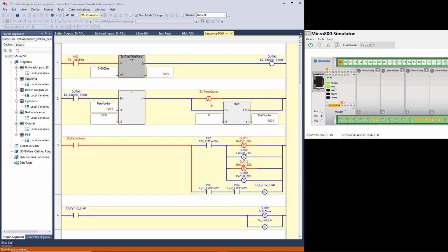do anything further, technically this part has gone through photo I1 and now it's going to pass through photo I2, and if I don't react, it's going to go right on through and out of the system. So we turn off input 0 and we turn on input 1. As long as we do that in a reasonable length of time, we're kind of simulating, when we turn on input 0, the part didn't stop moving. It's still moving through the barcode scanner.